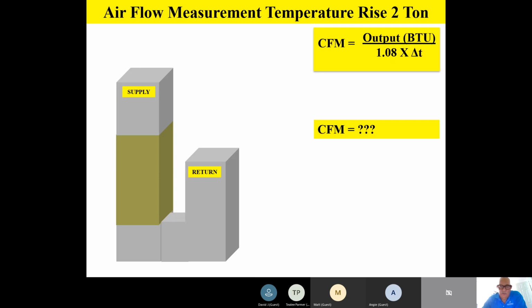Again, you know, a little bit of a formula. You have to plug in a little bit of math. So if I take on my calculator 28,563 divided by 35.6, what's the CFM? Anybody? Okay, I worked the math out and it was 802 CFM.